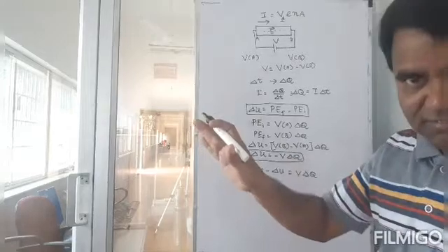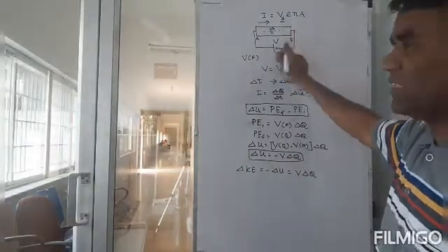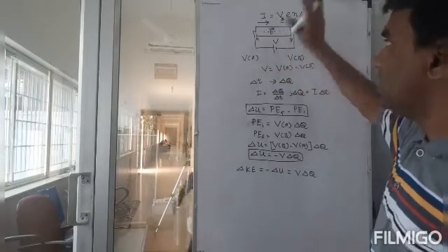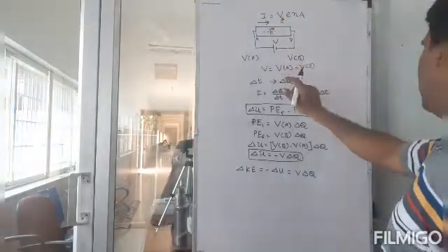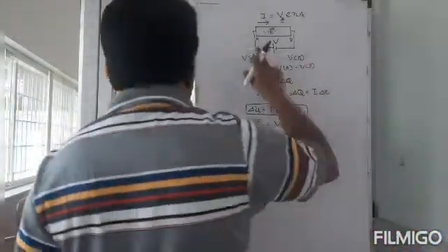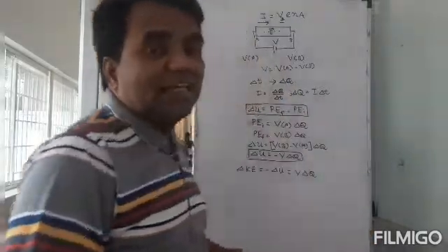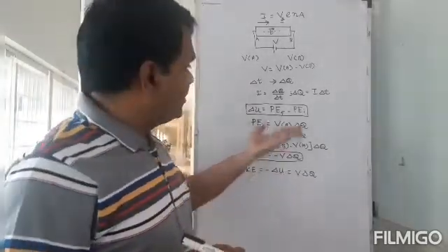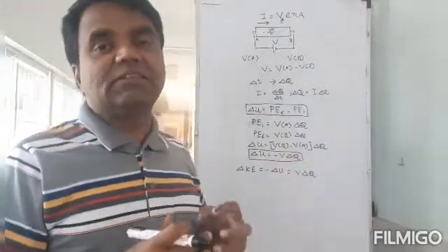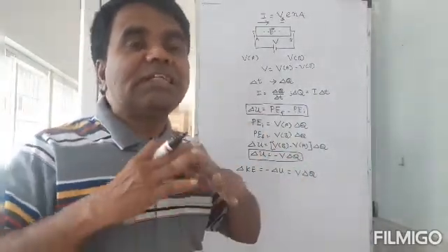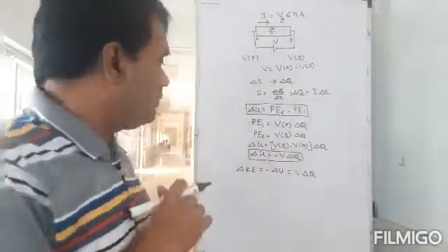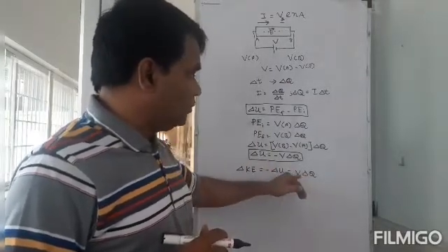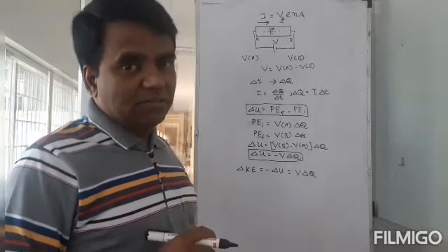You get a steady current, meaning that the kinetic energy has not changed at all because this V has not changed. It enters here with V, it leaves here with V. So the kinetic energy has not changed. But the kinetic energy should have been there, and it is not there. If it is not there, it's because it has been taken away by something else. What has taken it away? The atoms inside the conductor have taken this kinetic energy away and then release that energy as heat.